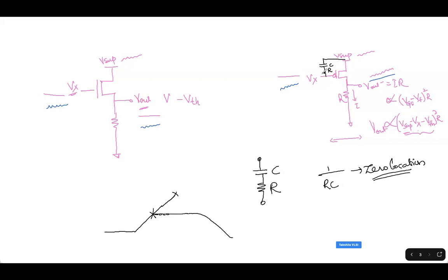Is there any other way that we can say that Vx should have noise or shouldn't have noise for both NMOS and PMOS? What if we use a 5T OTA? Typically, we use a 5T OTA here, right? Just connect like this. This may be a feedback coming from here. This is VREF. This is PMOS, and feedback is positive, and this is negative.